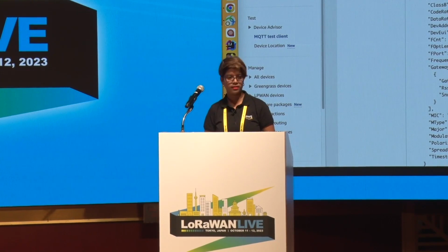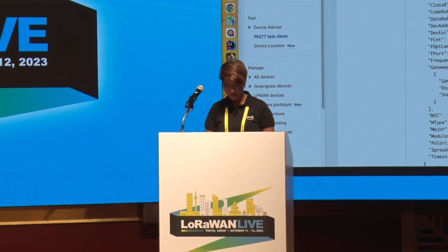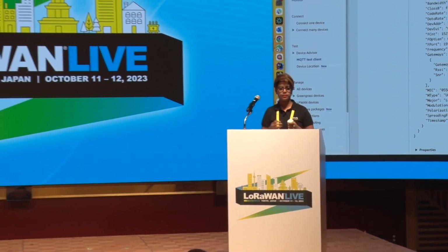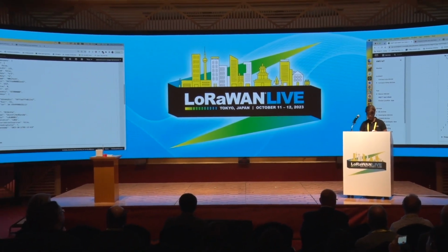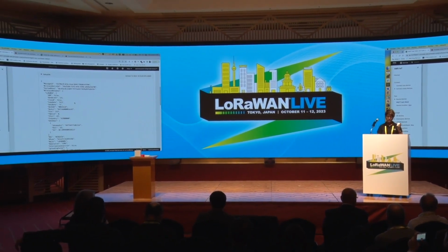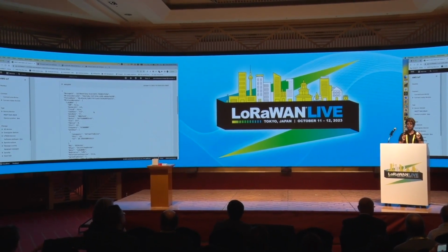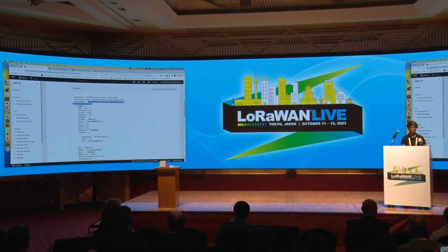That's the beauty about using the LoRaWAN, right? Because you're not going to consume a lot of battery with this if you're going to send this small, tiny amount of data. And these are the other metadata, like which class it uses, which F port, and here's the timestamp. So this is the raw payload that's coming from the device, but this doesn't have the latitude, longitude yet, because the payload has to be decoded.